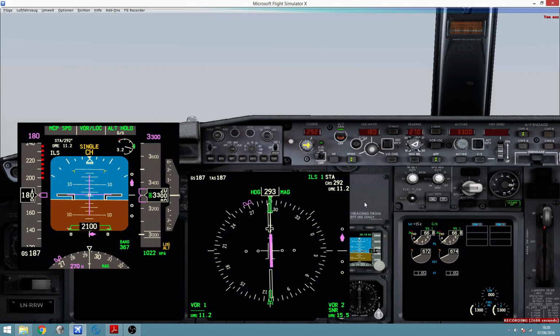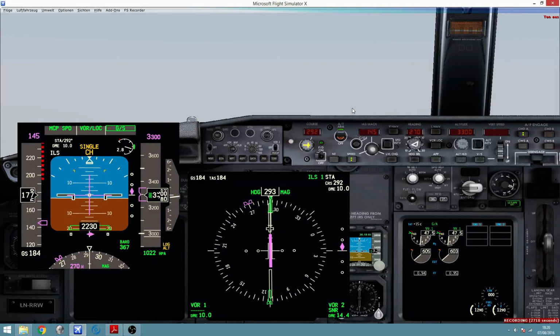So I'll prepare now the aircraft for landing. Go through the last of your checklist. The table 7 final approach point checklist says 145 knots, so I will reduce to 145. It says that flaps should be totally down, F8, and gear down, so letter G on the keyboard.